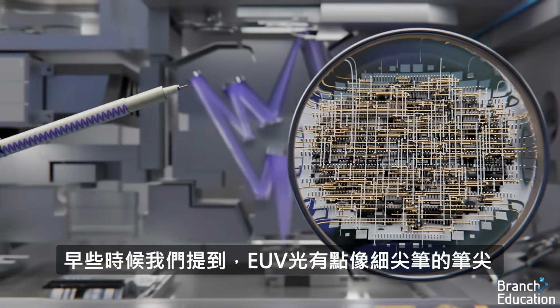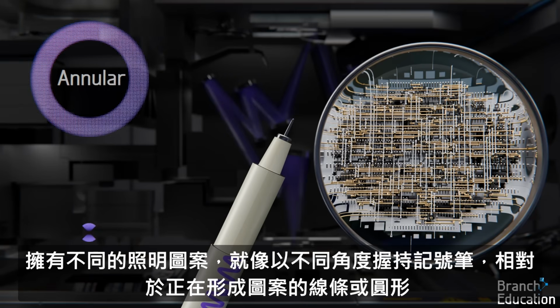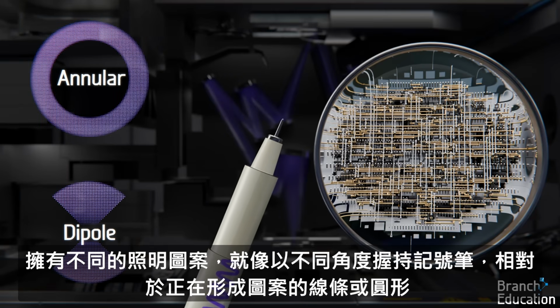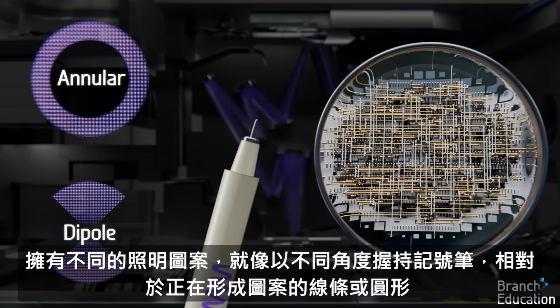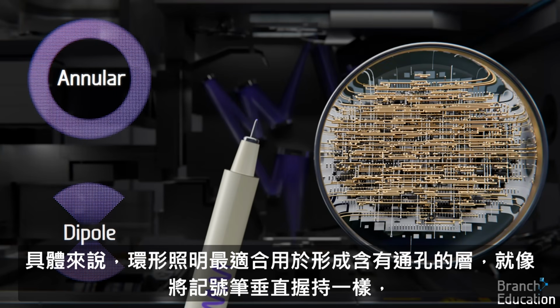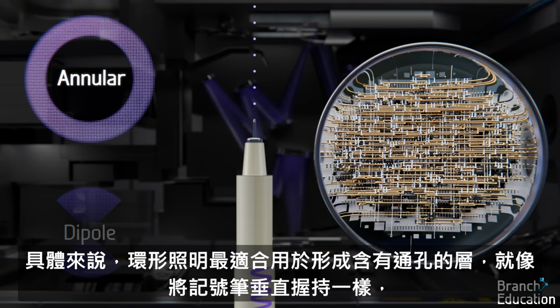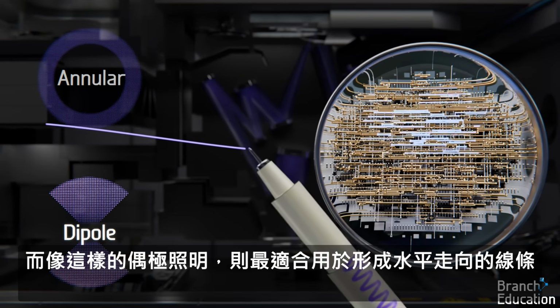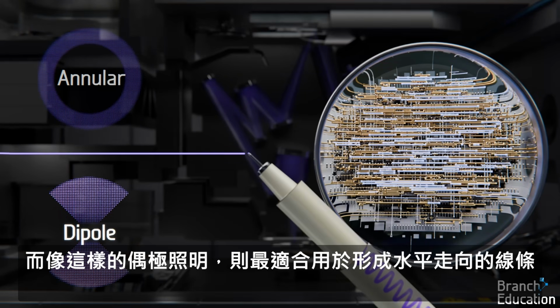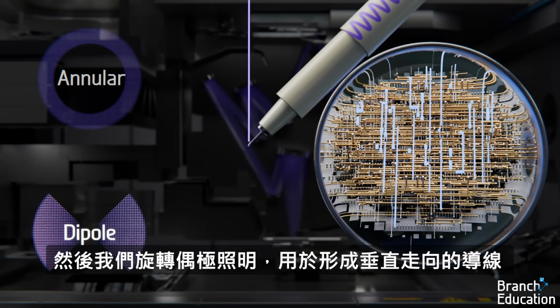Earlier we said that the EUV light is kind of like the tip of a fine-tipped pen. Having different patterns of illumination is like holding the marker at different angles with respect to the lines or circles that are being patterned. Specifically, annular illumination is best used to pattern the layers containing vias, and is like holding the marker straight up and down, whereas dipole illumination, like this, is best used to pattern lines running horizontally, and then we rotate the dipole illumination for patterning the vertically oriented wires.